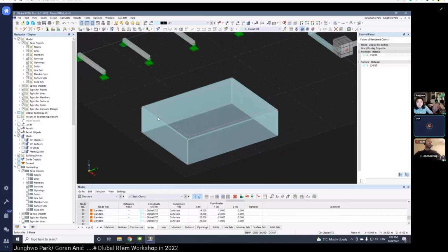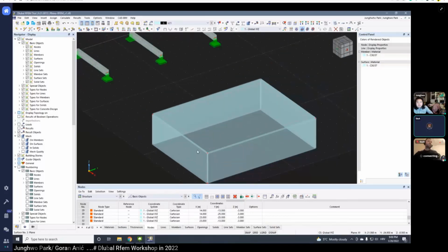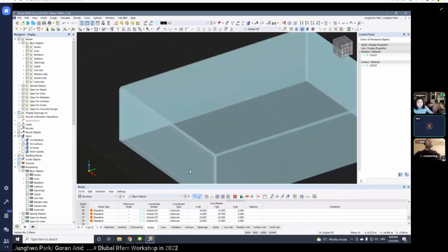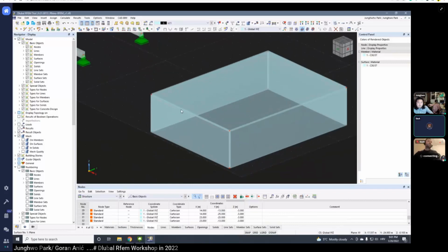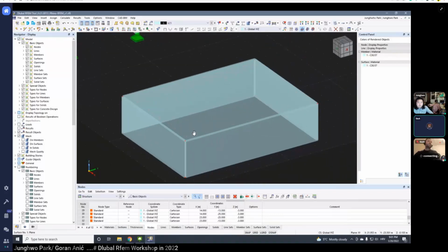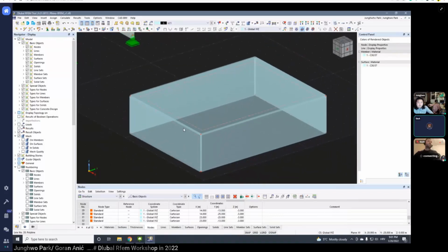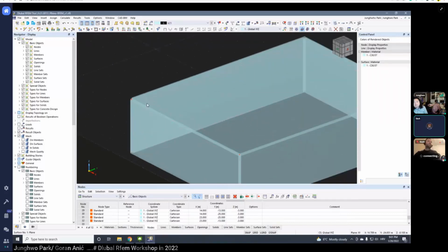Usually at the end you have to put some reinforcement bar that goes continuously from the wall to the slab in the top zone, and this position maybe is not very simple to implement on the construction site.